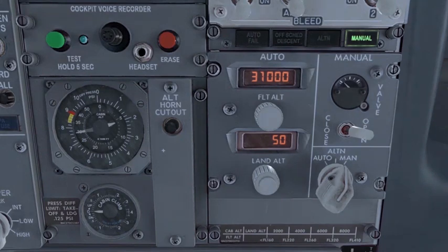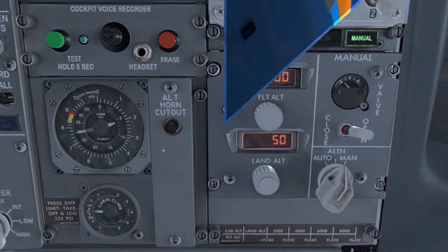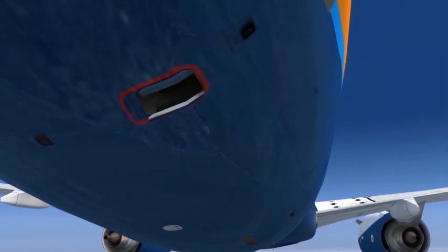To control the outflow valve manually, the pilots use the outflow valve switch in the cabin pressurization panel. This switch is spring-loaded to center, but has the following positions. Close. When the pressurization mode selector is in manual, it progressively closes the outflow valve. Open. When the pressurization mode selector is in manual, it progressively opens the outflow valve.